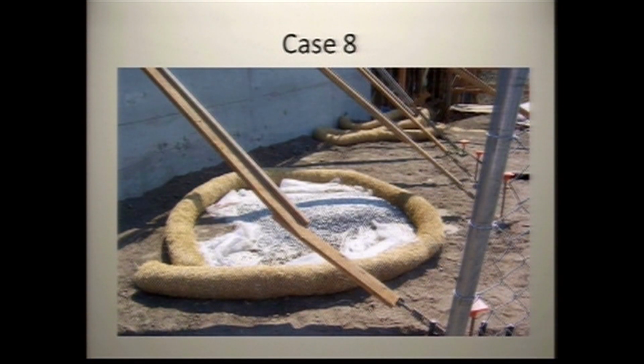What about this? Looks like a makeshift washout that lost all protection. Yeah, makeshift washout. So what's the basic fundamental design variable for a washout per the permit? Has to be watertight. This one isn't watertight. Why do they have to be watertight?